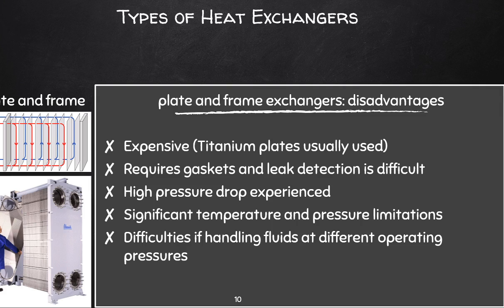Okay. Because of the requirement of gaskets for plate and frame heat exchangers, temperatures are also limited to about 250 degrees Celsius. You do get gaskets that can withstand much higher temperatures of 500, 700, the ones that we use in our pyrolysis applications. You can have a graphite lined gasket, but obviously you're going to pay a lot of money for these gaskets.